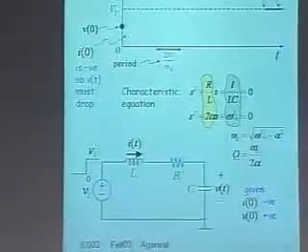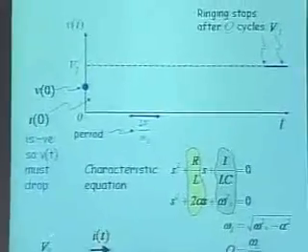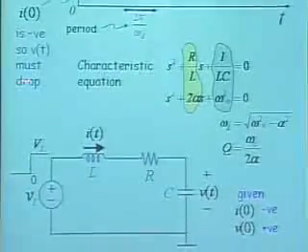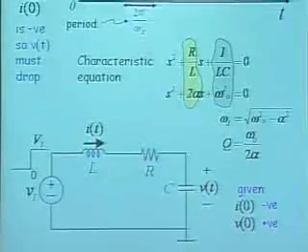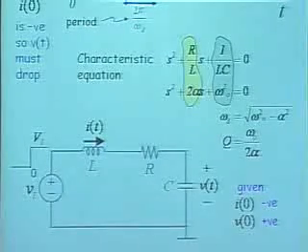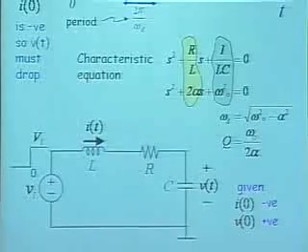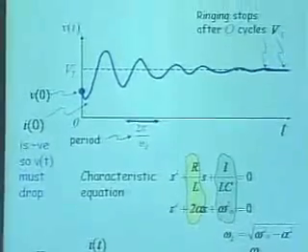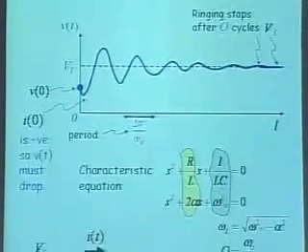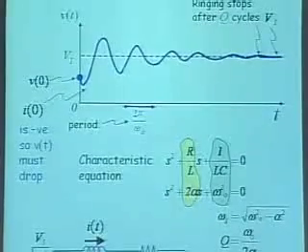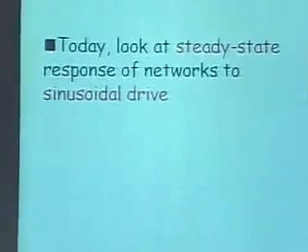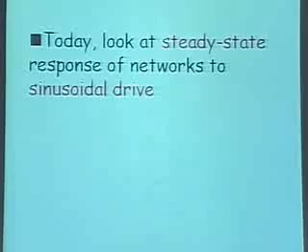So this means that I0 is negative. It's as if I0 is being pulled out in this manner, so the capacitor voltage must drop to begin life. And therefore the dynamics look somewhat like this. Notice that this is very reminiscent of the ringing that we saw at the input node of the second inverter, at the gate node of the second inverter. So let's stop here in terms of time domain analysis of RLC.